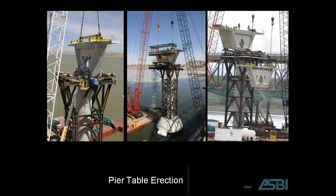Pier table erection occurs based from a barge and a crane. The crane lifts the segments up on top of the pier. There's some supports that are used to stabilize the pier segments. The pier segments are two halves, as I mentioned, because of the hauling weights, lifting weights, etc. Those segments are then epoxied and temporarily stressed together to provide a squeeze out of the epoxy. They match up to make the pier table.